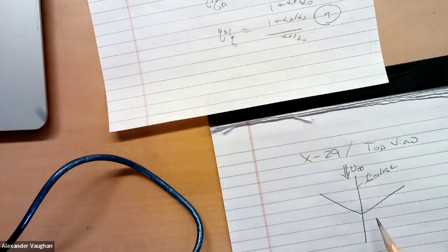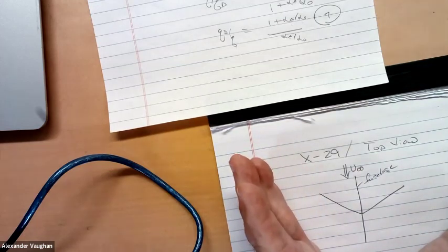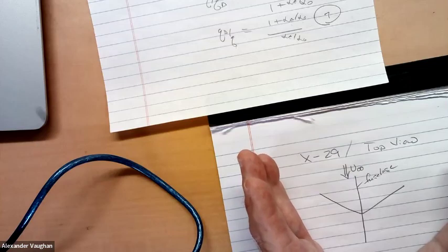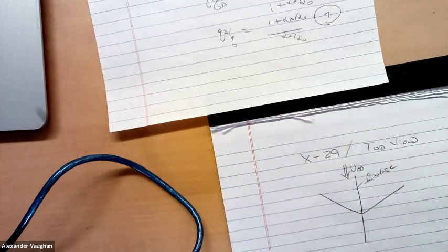he championed this idea. And this was when composite materials were first coming into the vogue. And it turned out if you build a plane out of metal, it was really hard to build a plane with a swept forward wing that was not so critical for divergence that it made any sense. By the way, the sweeping forward actually has better aerodynamic performance than sweeping back. Okay, so the reason we don't sweep forward is because of aeroelastics. But they did build the X-29. They used composite materials. They tailored it so that the stiffness was of a certain distribution, and they flew it. But no one said, let's go out and build 1,000 of these, right? They decided not to do that.